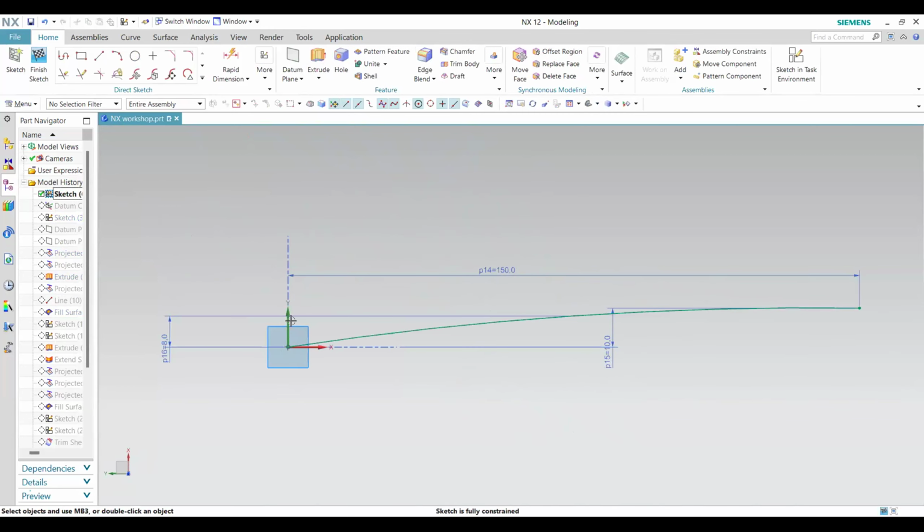So similarly, you take a line, and then you can use the curve option, the arc that you see here, to give a curvature profile, and this is how we dimension it. Basically, the designer, the one who has sketched it, is going to give you a design point of view as to how much this length has to be. It is 150 here that you can see. So you have to follow the same dimension that they have given.